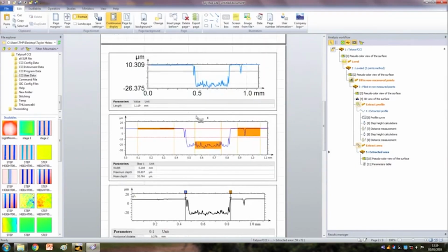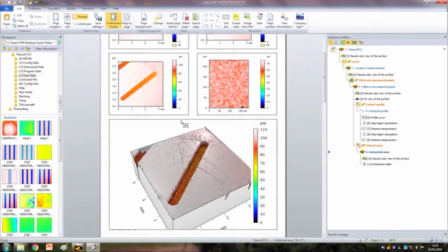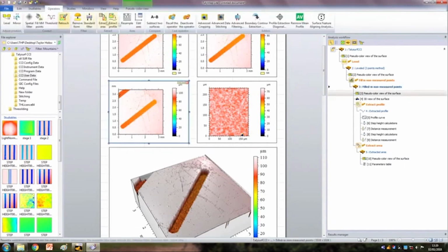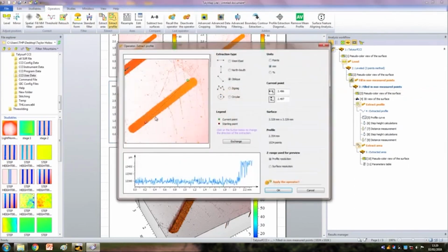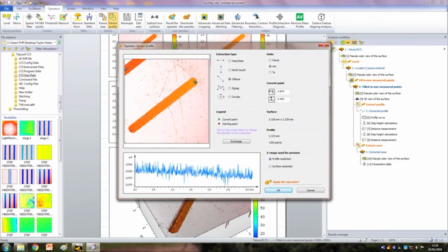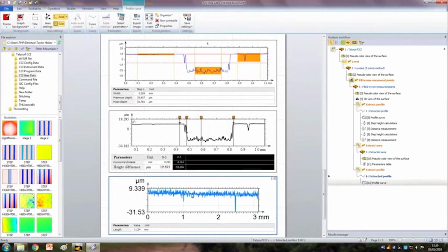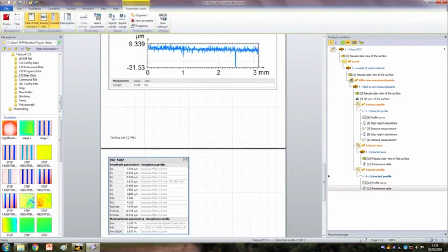And suppose you want to do measurement inside the area, that means along the line completely, then we select this particular parameter, then operate and select extract the profile. Then let us put one full line starting from the end. So this is the roughness line of the internal surface, that is the bottom surface. So this is the part. If you select this and then again go to the study and do the parameters, now it is giving you all the values related to the line roughness. So here the surface roughness is 1.9 micron, which is showing here in this case.